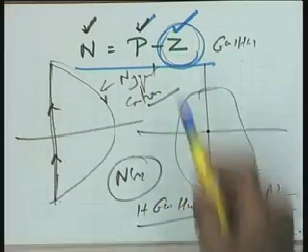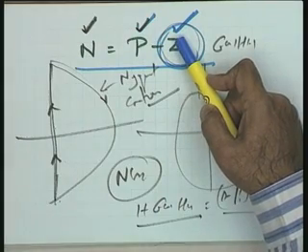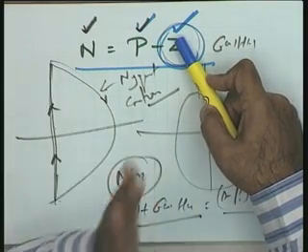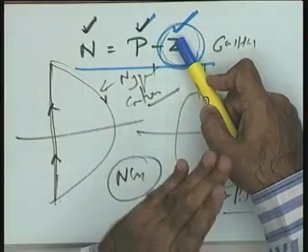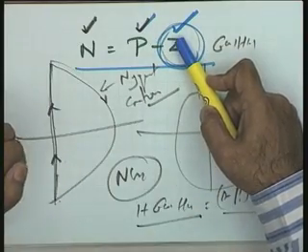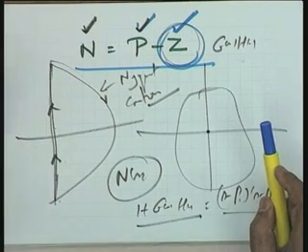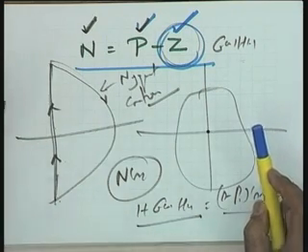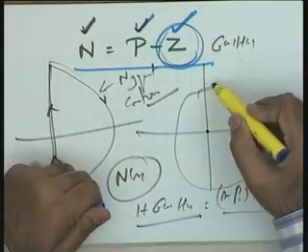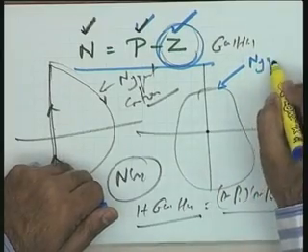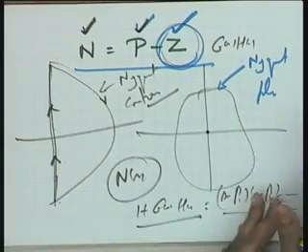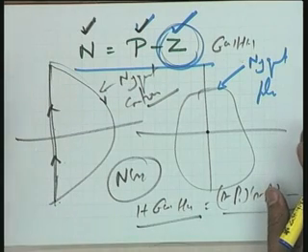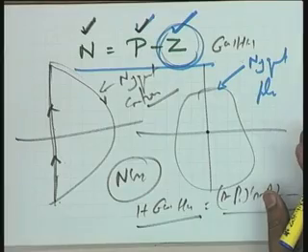If, and you know that for stability Z equal to 0, where Z is the number of closed loop poles in the right half plane. For stability Z has to be equal to 0, so for an open loop stable system, stability requires that the Nyquist plot in the GsHs plane, the Nyquist plot in the W plane, does not encircle the origin.